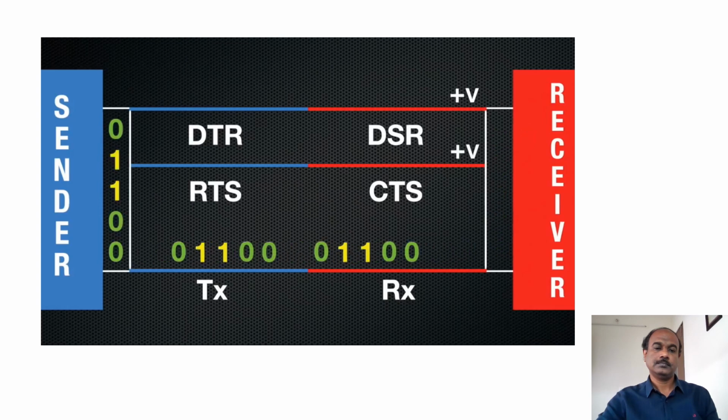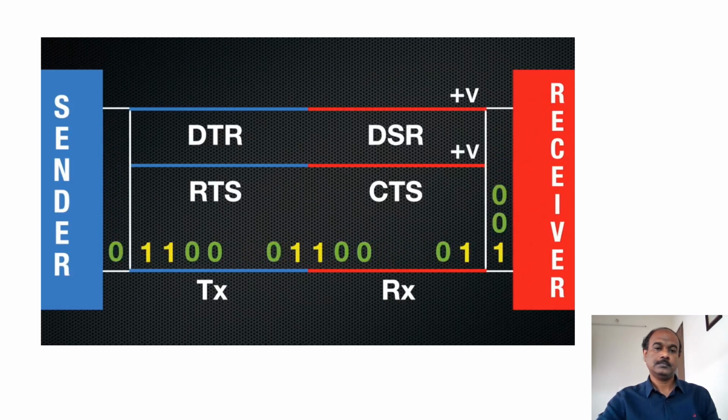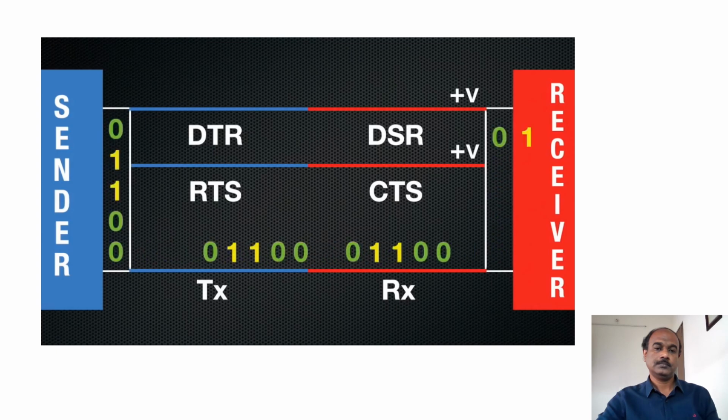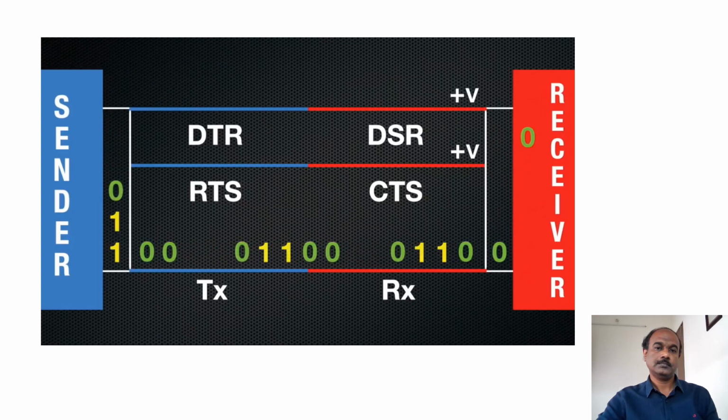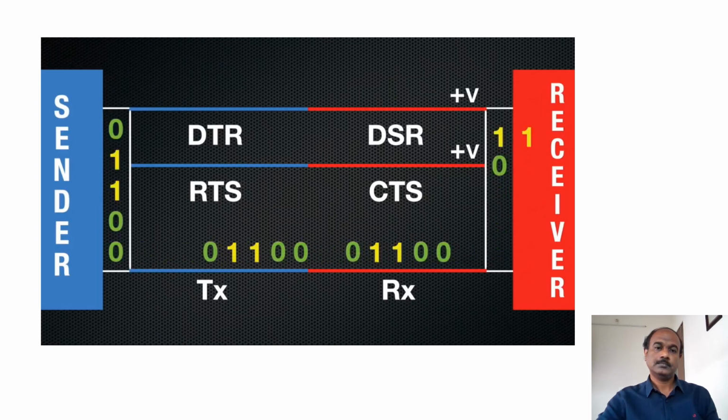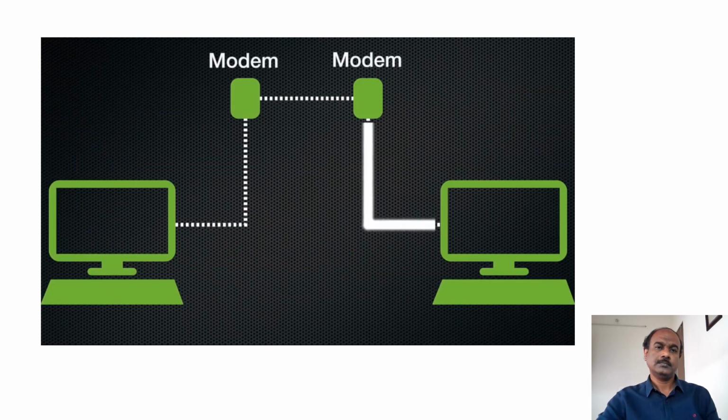Using this send-stop signal is known as hardware flow control. The RTS-CTS wire is the hardware that controls when data flows between the devices. For completeness' sake, there are two more wires defined in the RS-232 spec. Both of these are related to modems, so seldom used anymore.